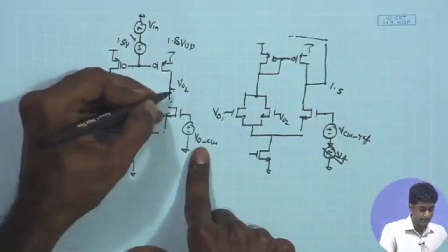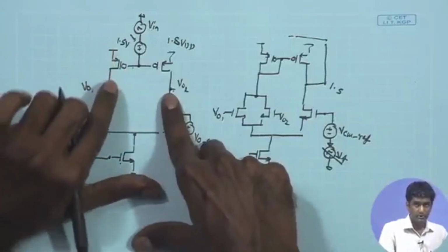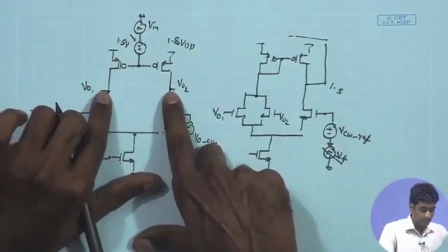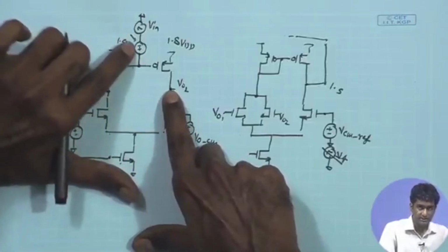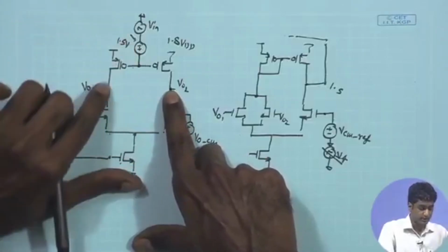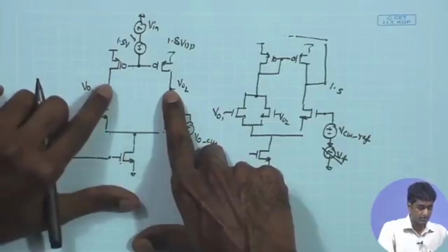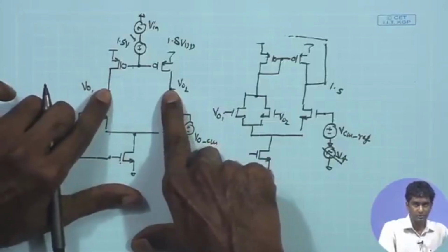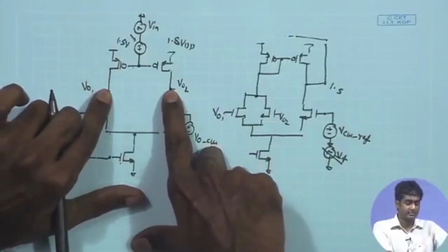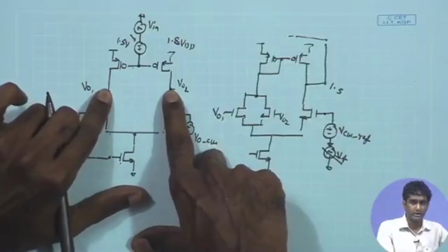Now, if we therefore want to look at the signal over here, a small change in the DC level, even 1 millivolt of change, can produce a large shift in the DC potential over here. So, remember, we are designing this circuit for an overall gain of greater than 10 to the power of 4.